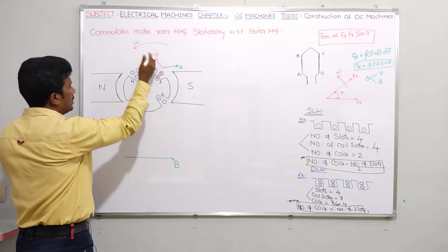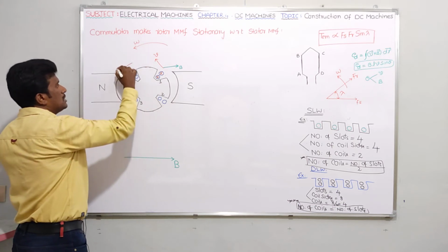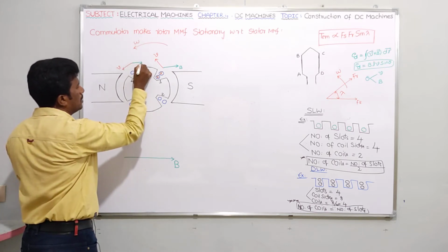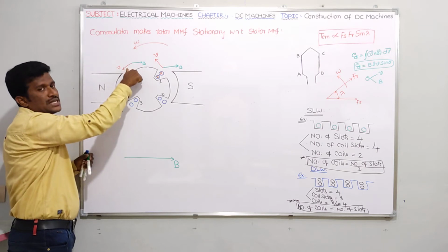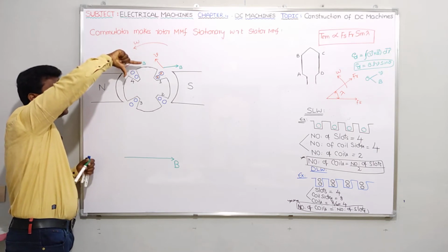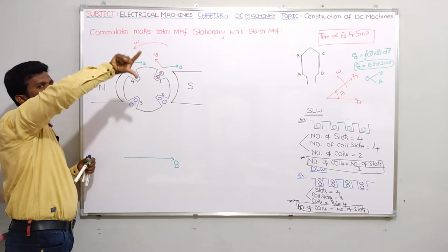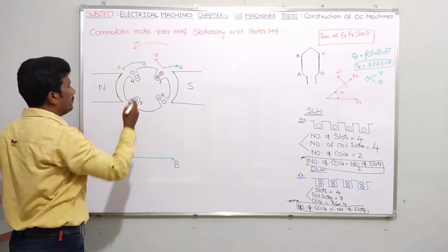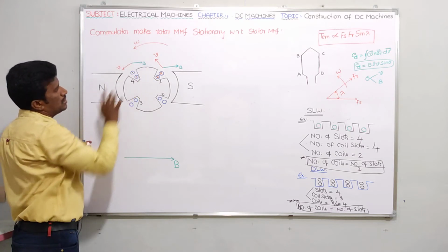Okay. Once again, it is rotating in anti-clockwise direction. It is coming like this, and at the fourth slot, this is the direction of linear velocity. And what might be the direction of flux density? This one. So please apply. When a moving conductor, thumb means direction of motion of the conductor, I can say direction of this red color arrow mark. Forefinger means direction of flux density, or I can say direction of this green color. EMF or current is induced in that conductor. Out of the board, this center finger is coming from the board. Coming from the board means what? You should take dot. So direction of current or EMF induced in slot number 4 is dot. Okay, guys. Once again, here also if you observe, it will be around 135 degrees only here also.